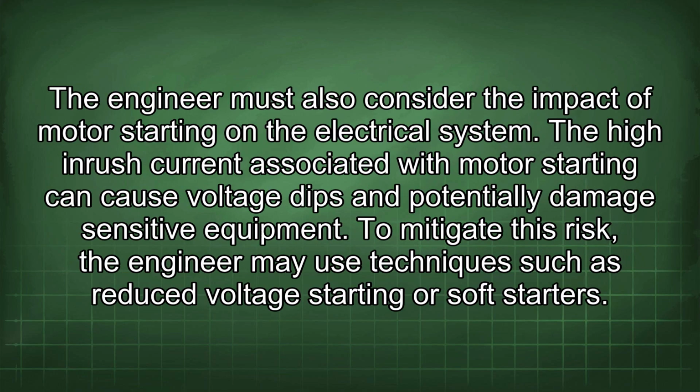The engineer must also consider the impact of motor starting on the electrical system. The high inrush current associated with motor starting can cause voltage dips and potentially damage sensitive equipment. To mitigate this risk, the engineer may use techniques such as reduced voltage starting or soft starters.